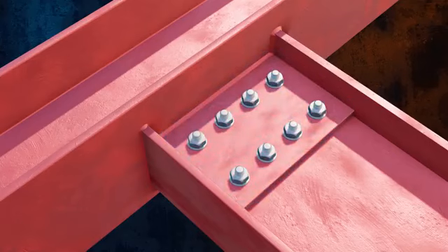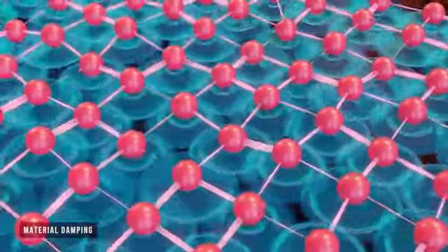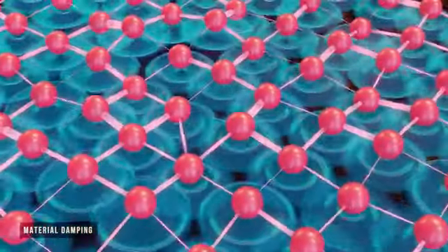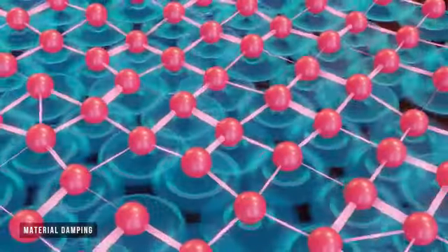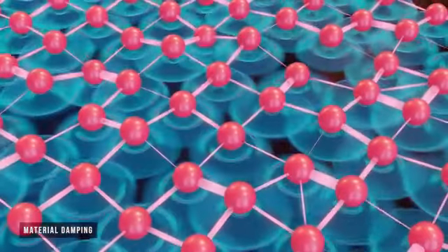And material damping is damping provided by the material itself, where energy dissipates in a vibrating material due to interactions occurring at the molecular level. To improve our spring mass model, we can lump the damping from all of the different sources together and represent